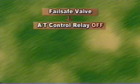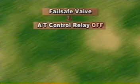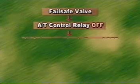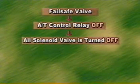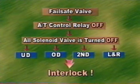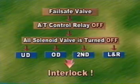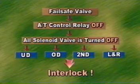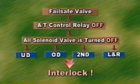Let's look at the oil pressure flow in fail-safe condition. If fail-safe condition is met, power supply to all solenoid valves is disconnected because of auto control relay turnoff. Since all solenoid valves turn off, if the driver selects driving forward range, oil pressure is supplied to all clutches and brakes, except reverse clutch, where oil pressure is mechanically supplied.